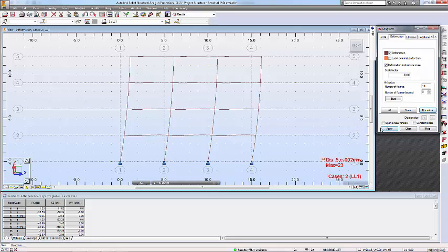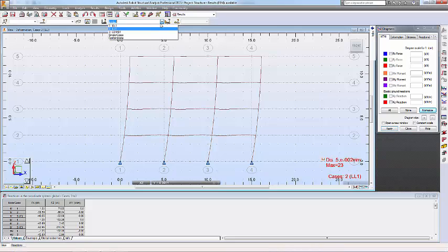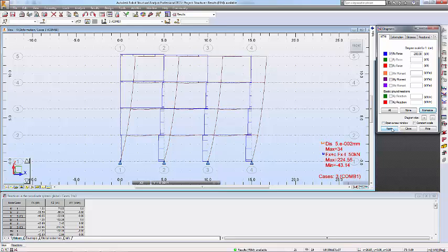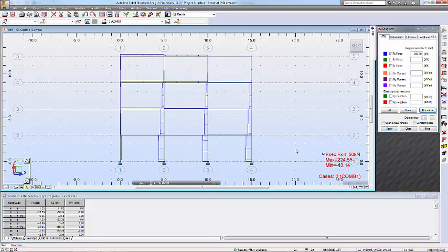And once we got this one, you can also have a look at the other bending moments. Say for example, this is the live load, and then that was the combination. So if you combine both together, you will have these structures. You see, the beam deforms quite little, and mainly it is the lateral deformation from here. So you can also have a look at axial force. So if you click on apply, then you see the lateral force, but we enabled this one, so you can see the axial force directly.